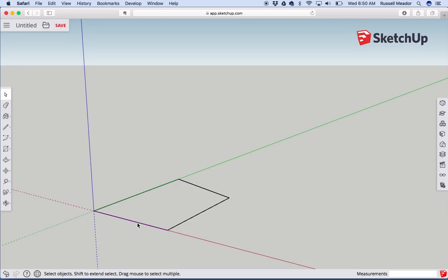So you see where they turn blue when I click this pointer is selected. So I can click and do that individually, which is a little tedious, particularly with the larger model. So I'm going to bring those back. You can undo anything in SketchUp by just hitting undo. I use a Mac, so Command Z is going to bring everything back.